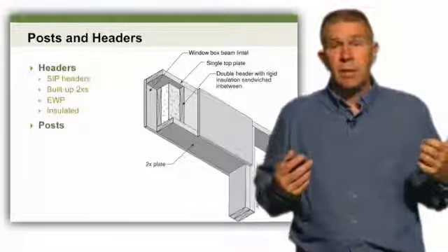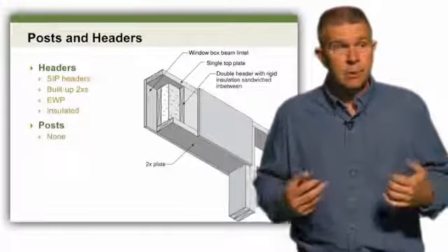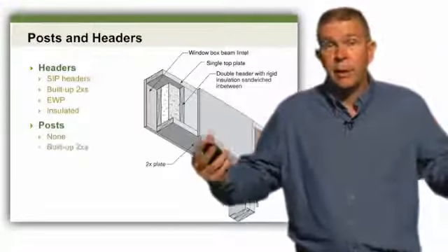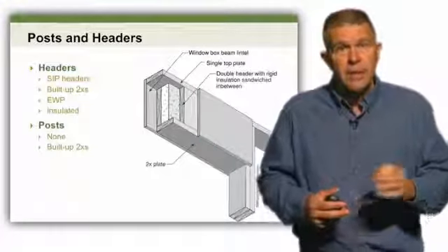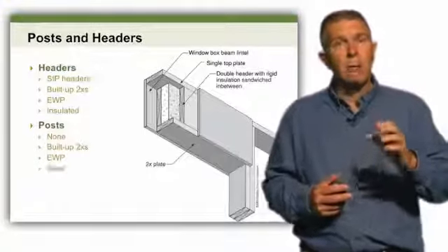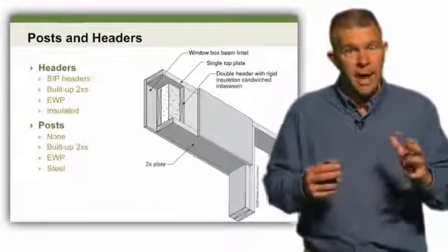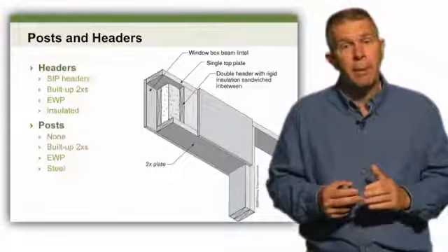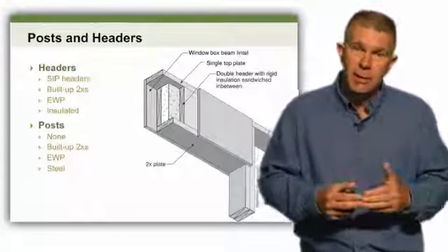Well, does it need to be a post, a jack post? Does it need to be incorporated into the wall panels on either side? These are things that the engineer looks at using the data that is provided by the SIP provider. They have the load design charts to know what their panel has been tested and what it can carry.